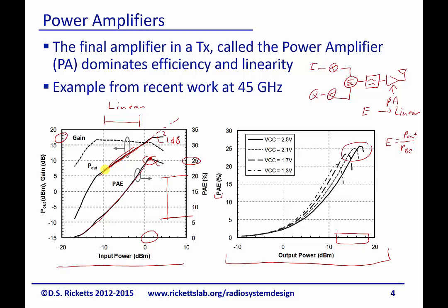For an amplitude modulated signal, we have to make a trade-off between efficiency and linearity, and we just bite the bullet and operate down here because we can't handle the spectral growth and the harmonics that are created. However, there are some architectures, which we'll talk about in a minute, which can operate at a constant amplitude. If they can do that, then we can pick any amplitude on this curve to operate, and why not choose this one right here, which would give us the highest efficiency.